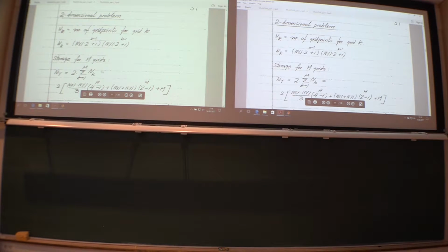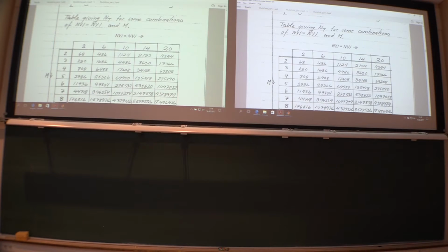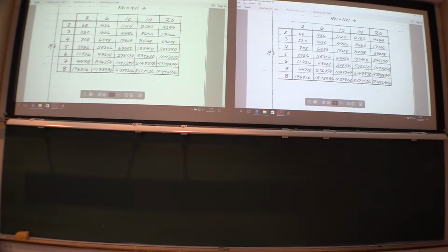But also in 2D, of course, even worse. So you have to be careful if you want to define the problem like this, starting on the coarse mesh and then say, I want 8 mesh levels. Then you blow the memory on the fine mesh fairly easy. How big is this number? 17 million unknowns, thank you. You need a big computer already.